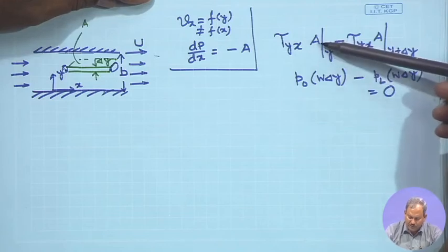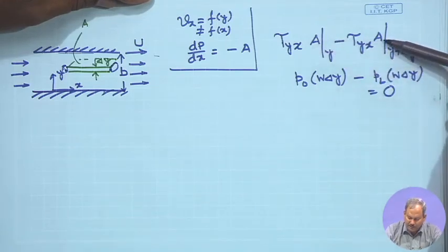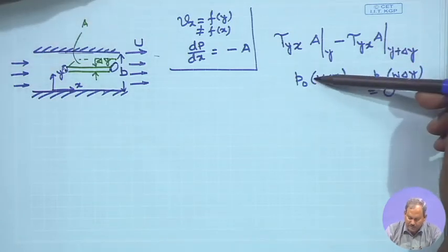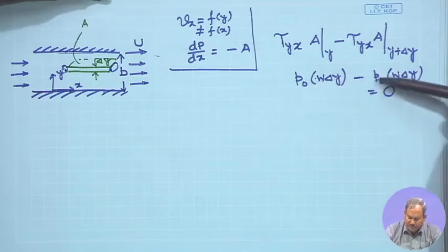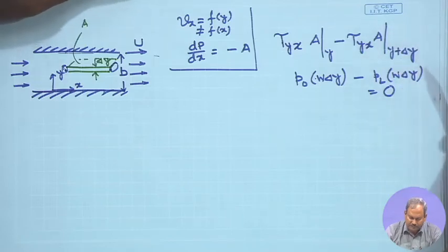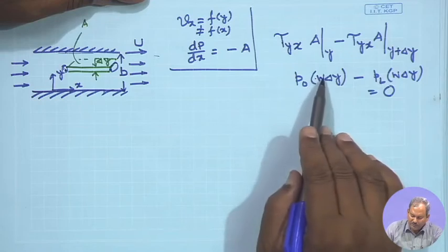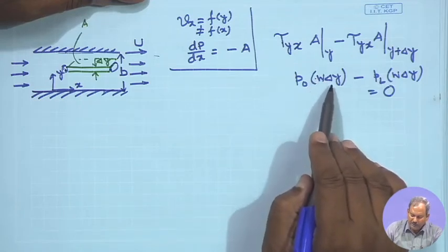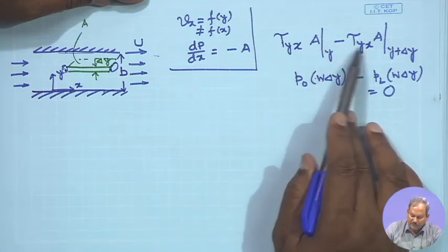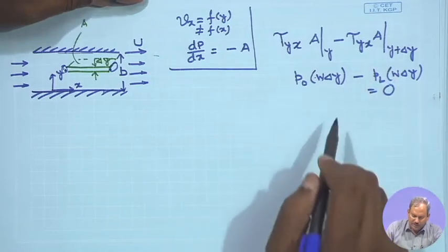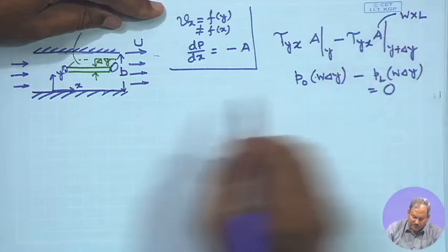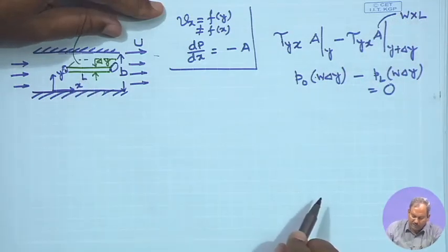So, viscous momentum in minus viscous momentum out, no convection terms, no gravity term, no body force term, and the force due to pressure: at steady state the sum of this is going to be equal to 0. So, again we divide both sides by delta y and take the limit when delta y approaches 0. So, what I would get out of these two terms is minus d dy of tau y x, and essentially this area is nothing but W times L, where L is the length of the control volume.